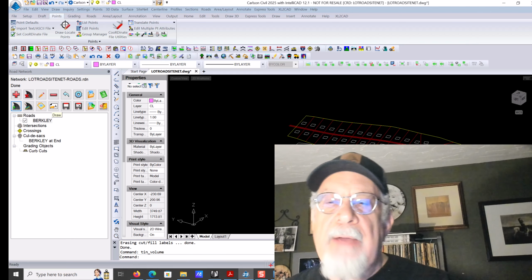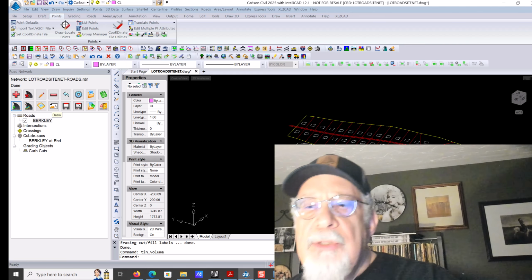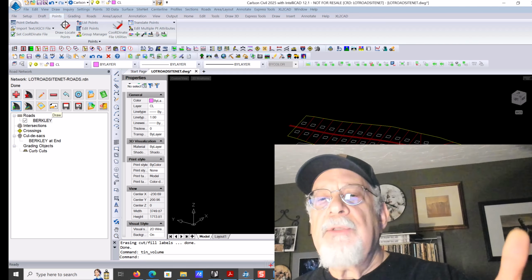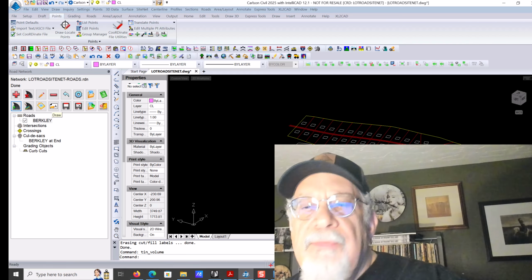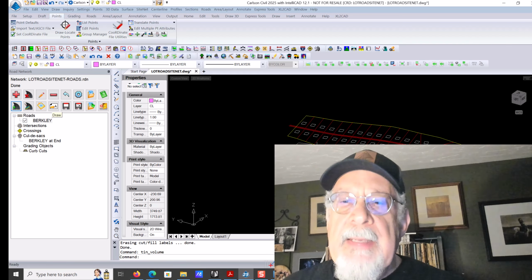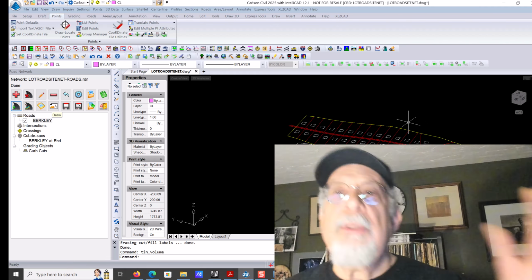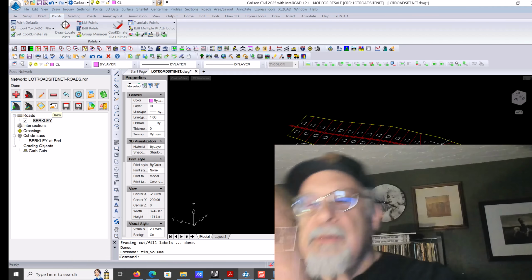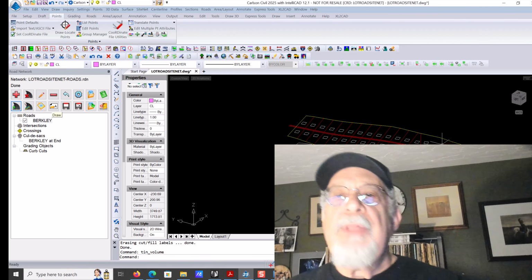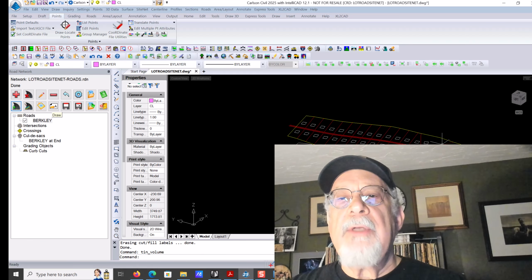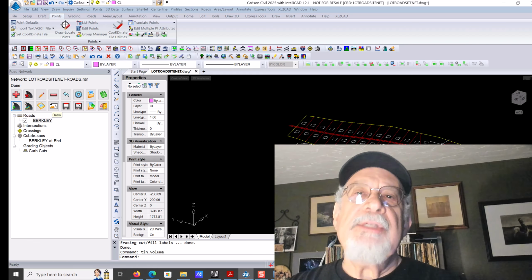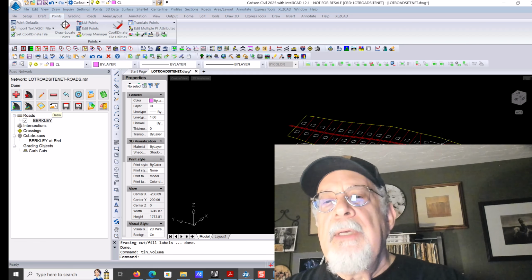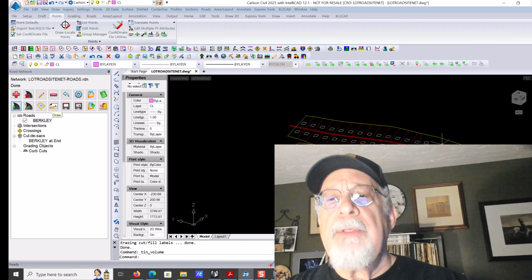I could go back and do the lots again. I'm out of time now for sure. But I could go back and change to 1 acre lots, elevate the roads, elevate the lots, change the building pads, change the foundation depth, whatever. LotNet to RoadNet to SiteNet to LotNet to RoadNet to SiteNet. These 3 pieces work together, my friends, and you can do some spectacular conceptual preliminary design and get some ideas of what you want to do.